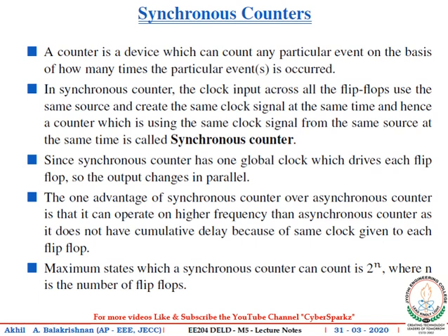Synchronous counters are counters in which all the flip-flops are triggered simultaneously, that is, in parallel by the clock input pulses. Whether a flip-flop changes its state or not depends on the flip-flop's inputs, that is JK, D, T or SR. Since all the flip-flops change state simultaneously in synchronization with the clock pulse, the propagation delays of flip-flops do not add together as in ripple counters to produce the overall delay.